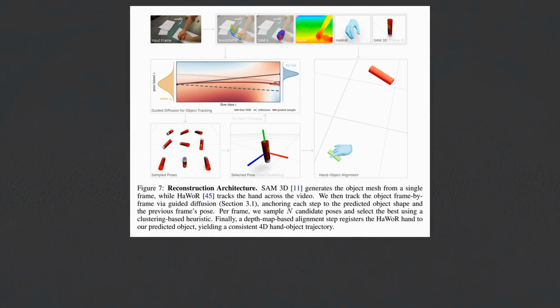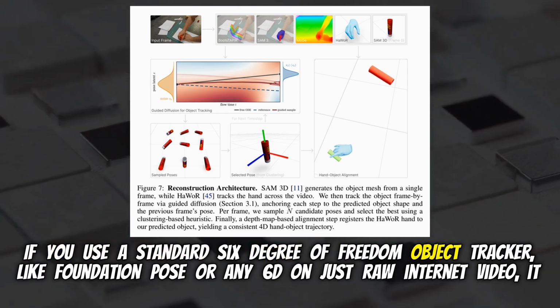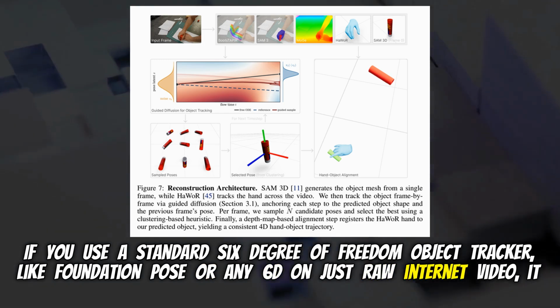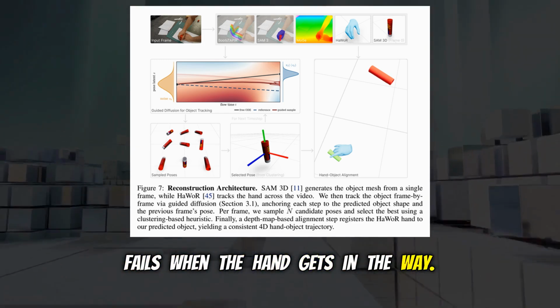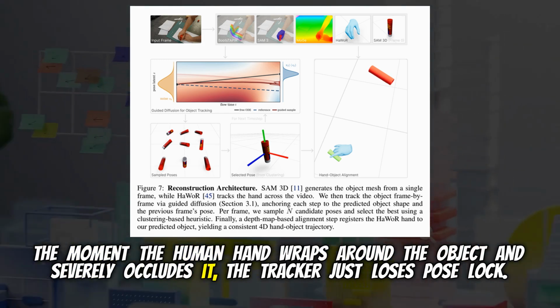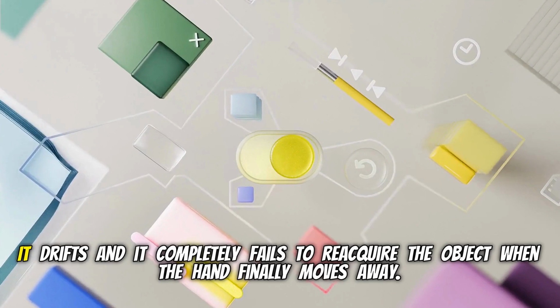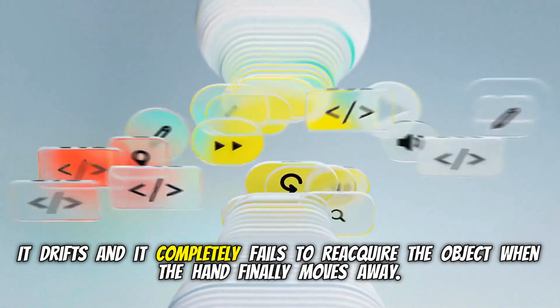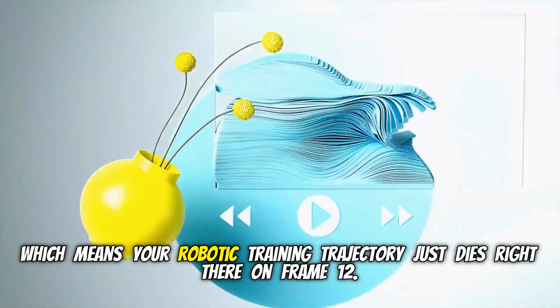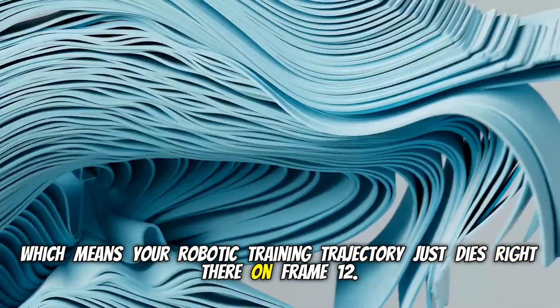Oh, absolutely. If you use a standard 6 degree of freedom object tracker like FoundationPose or any 6D tracker on just raw internet video, it fails when the hand gets in the way. Right. The moment the human hand wraps around the object and severely occludes it, the tracker just loses pose lock. It drifts, and it completely fails to reacquire the object when the hand finally moves away. Which means your robotic training trajectory just dies right there on frame 12.